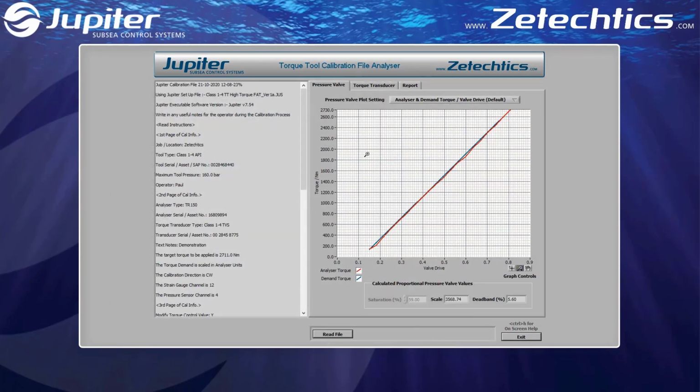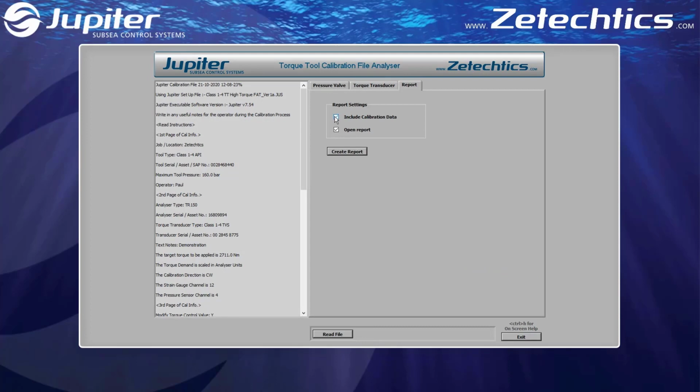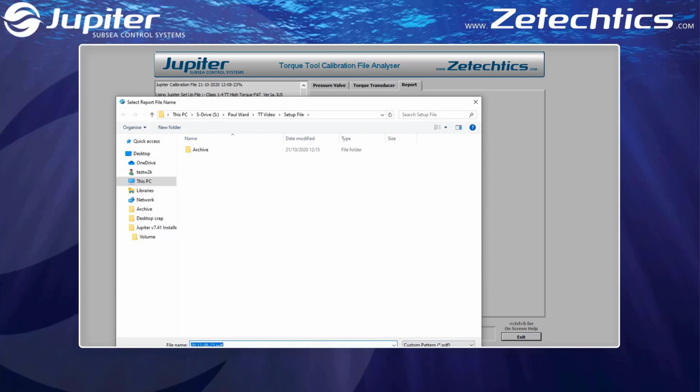A number of graphs can be viewed, as well as the contents of the file, on the left hand side. Go to the Report tab, select Include Calibration Data to see a table of torque versus pressure on the report. If Open Report is ticked, then the file will open in the default PDF reader when it has been created. Click Create Report and choose where to save and what to name the file.